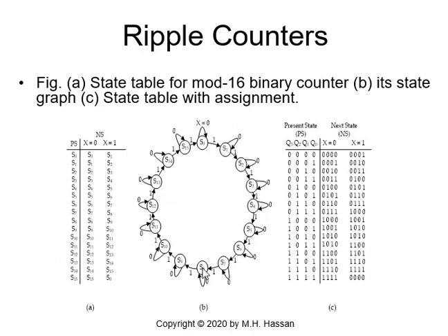So we really have 16 states, from S0 to S15 and back to S0. Accordingly, we will have the present state S0 to S15, and the next state: when X is 0 it will remain at the same state, but S0 with X equal to 1 will go to S1, S1 with X equal to 1 will go to S2. And this will be the next state table.